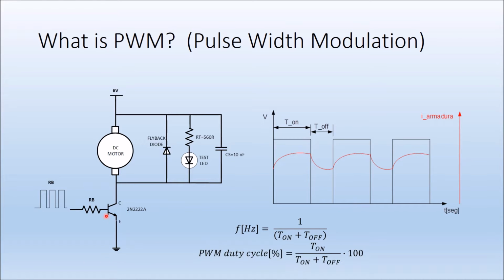So you can have from 0% duty cycle to 100% duty cycle, and at 100% you're at full velocity, and at 0% the current will not flow through the transistor, and the motor will not rotate. And values in between will give velocity in between these two boundaries.